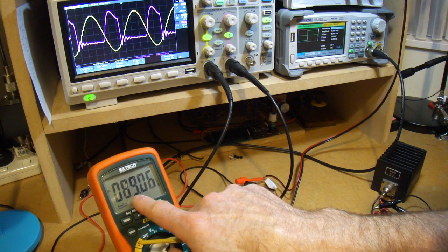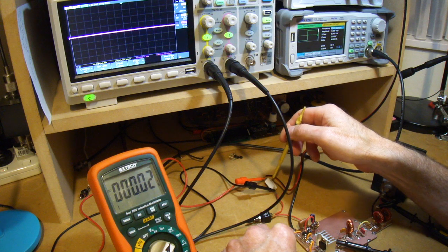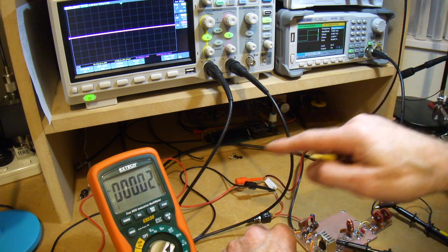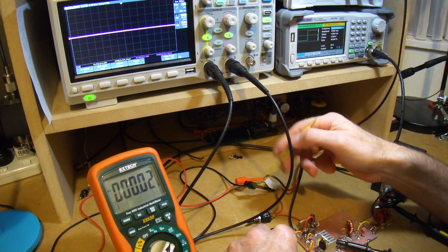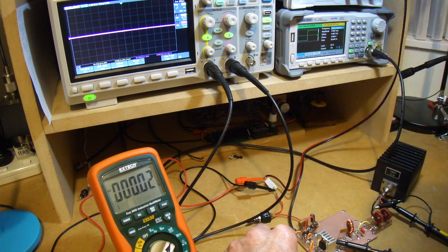And if we look over here, I'm getting 90 millivolts. So 90 millivolts divided by 0.1 ohms comes out at 0.9 amps. So 0.9 amps times 12 volts, which is the VCC coming in. I'm now consuming 10 or close to 11 watts of power from the battery, in this case, or the power supply. But I'm getting 7 watts out. So 7.2 watts out. Let's round that to, well, I use 10.8. 7.2 divided by 10.8 comes out at 66%